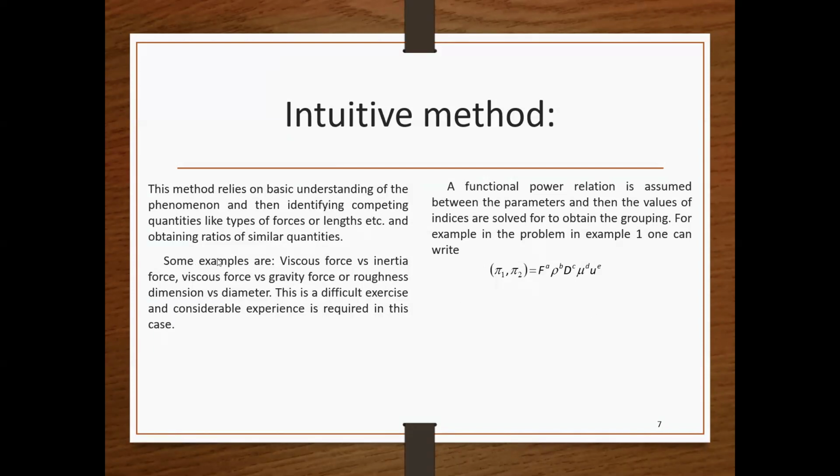Some examples are viscous force versus inertia forces, viscous force versus gravity force, or roughness dimension versus diameter. This is a difficult exercise and considerable experience is required in this case.